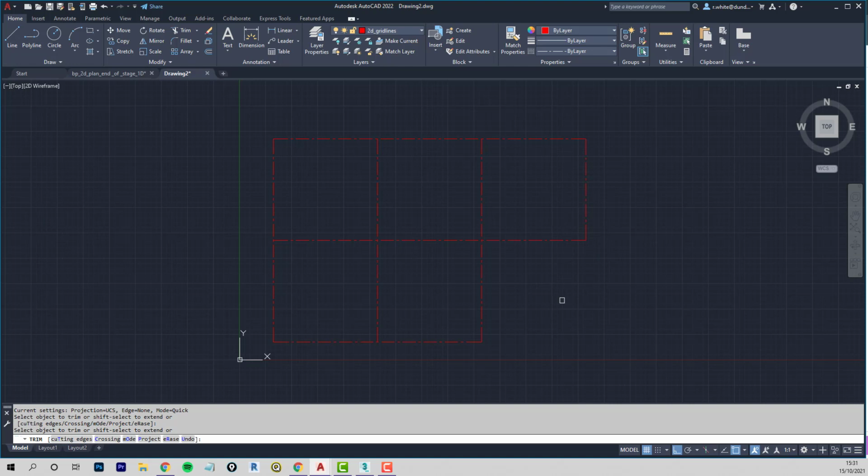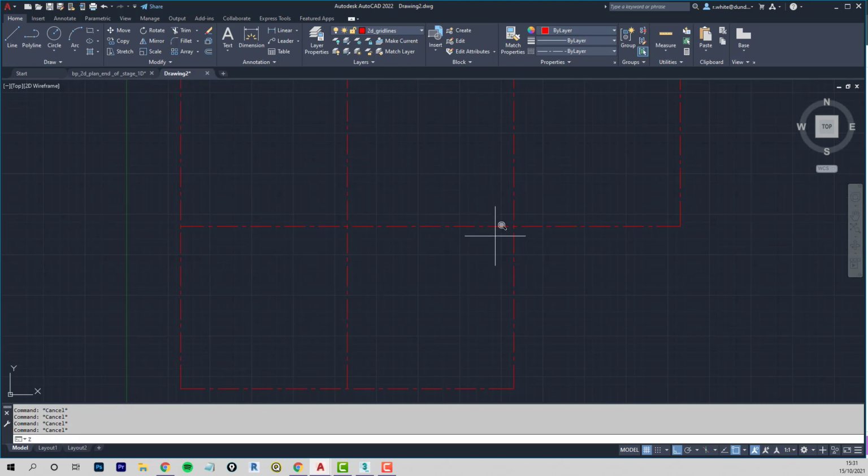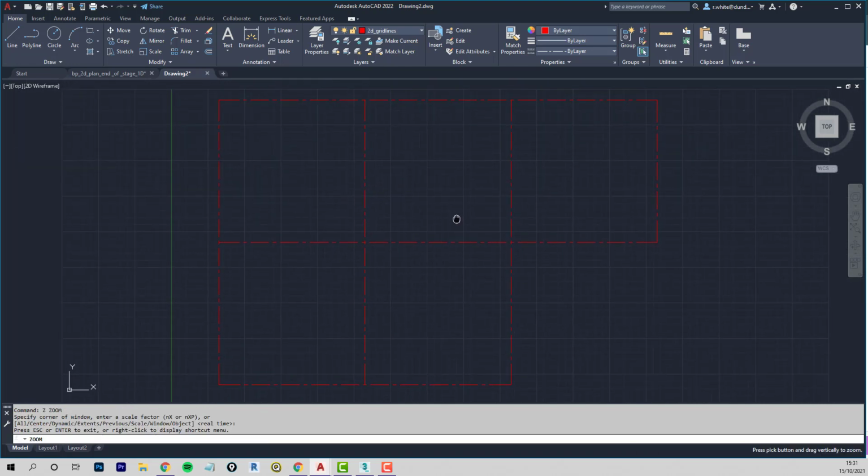Easy to use. Okay, fillet. If I just extend these, the good thing about fillet is that it does the trimming as well. So you can have a situation where one object is too long and one is too short. If you fillet that, it tidies both lines up at the same time. So my advice with people is, okay, use trim and extend, but start using fillet and you'll be much more efficient. You will be quicker in the long run.